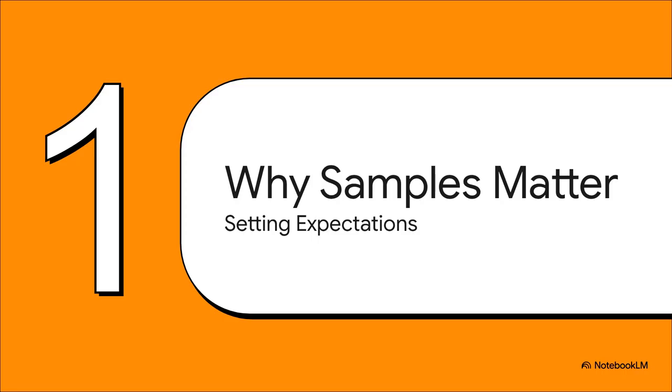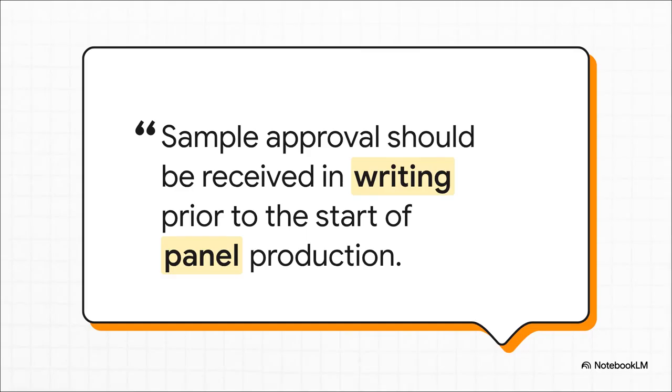So let's start with the big why. When you use them right, project samples are your best defense against really expensive arguments, change orders, and rework. Their whole job is to get everyone, the precaster, the architect, the owner, looking at the same thing and nodding their heads in agreement from day one. And listen, this isn't just a friendly tip. The quality manual is crystal clear here. Getting that approval in writing is a mandatory step. It makes the agreement official, and it protects you, the producer, just as much as it protects the client.